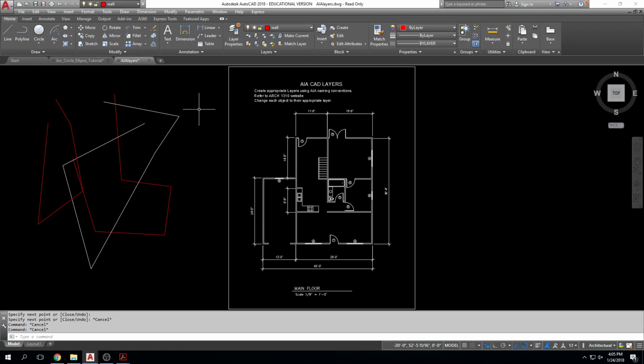All of these layers are transparent, and when I look at them in AutoCAD, I can look down, I can see all of them together, right? So it's as if I'm just stacking these transparent pieces of paper one on the other, and I'm viewing all of them at the same time, right? But they're all separate and they can be turned on and off separately, and they all have different pen weights associated with them, okay? So for example, let's create a few more layers here.